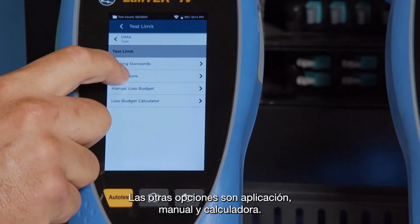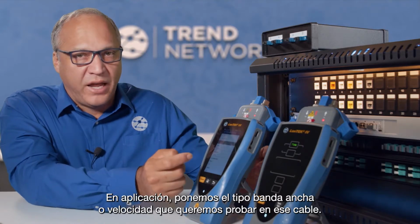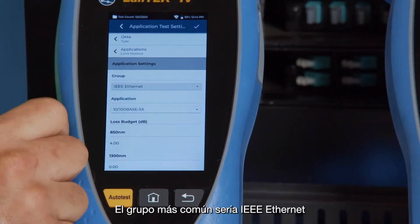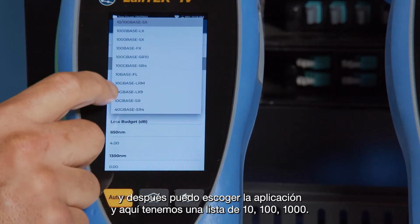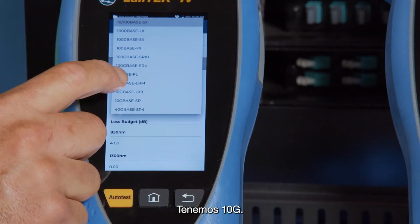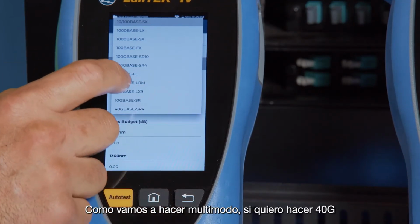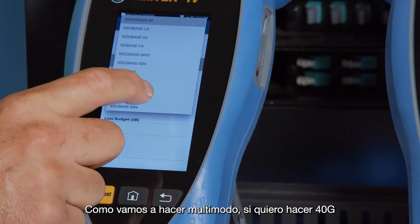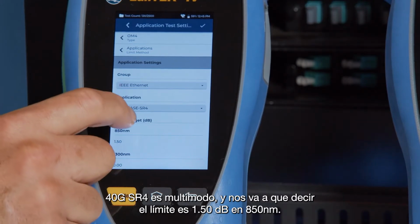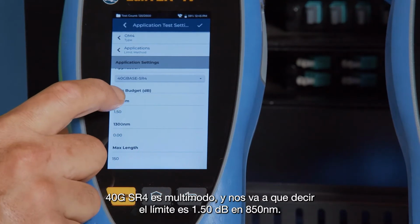The other options are application, manual, and calculator. So if you look at application, this is going to be if you know what particular bandwidth or speed needs to be tested on that cable. So a most common group would be IEEE Ethernet, and then I can choose the application here, and we have a mix of 10, 100, 1000, we have 10 gig, 40 gig. So there's various applications here. So if I wanted to do 40 gig, we're doing multi-mode here. So 40 gig SR4 is multi-mode, and that's going to tell us the limit is 1.50 dB at 850 nanometer.